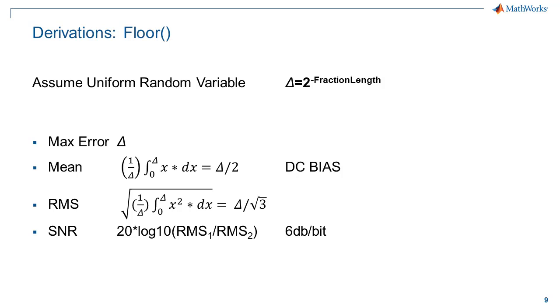The main thing here with the root mean square and the signal to noise ratio is that's where you start to get this concept that a lot of people have as a rule of thumb, which is that you get 6 dB per bit. So if you think in terms of a noise floor in the frequency domain in particular, every time you add one more bit of resolution, you can see the noise floor actually improve on the order of 6 decibels per bit.